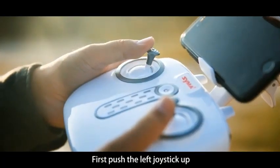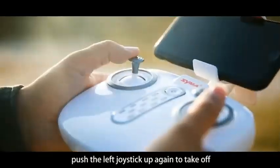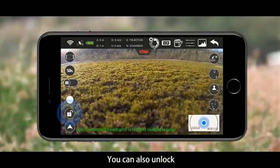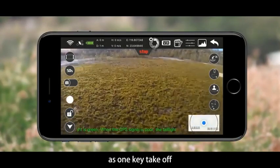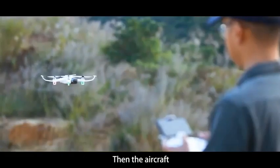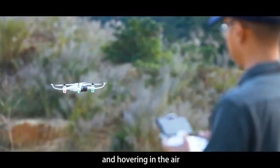First, push the left joystick up. When the propellers are spinning, push the left joystick up again to take off. You can also unlock and click the triangle button at the left bottom corner for one key takeoff. Just swipe to the right to confirm. Then the aircraft automatically takes off to a certain height and hovers in the air.